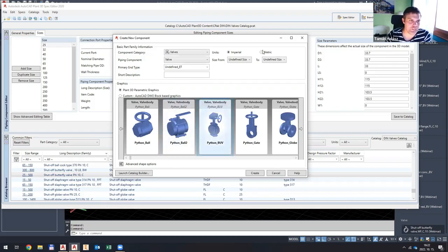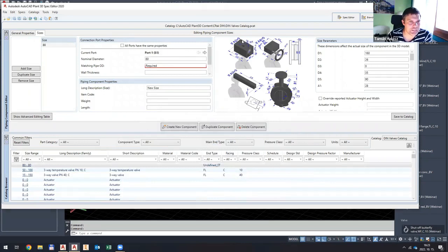So if I hit create on one of them, I don't know, DN80, 3-inch, this is the one I want to create. You can see there are so many parameters. At first it's maybe even too complicated. This is the valve body parameters. It is common for every kind of actuator. So you can adjust basically the whole geometry here. And based on which A parameter is not zero, you can define different kinds of actuators here.